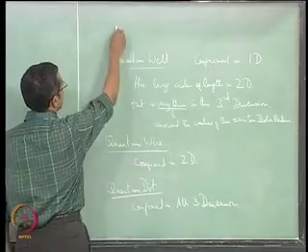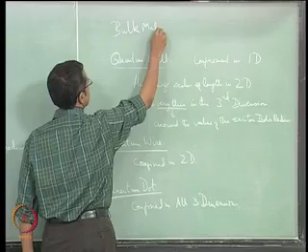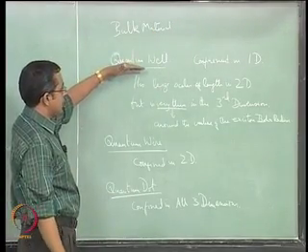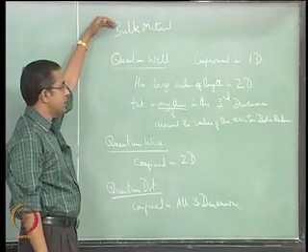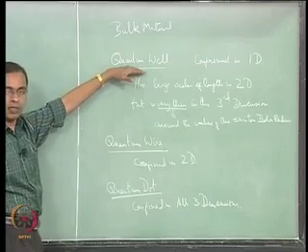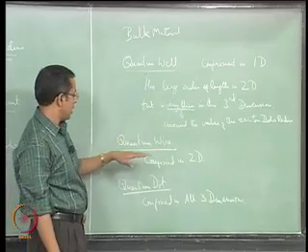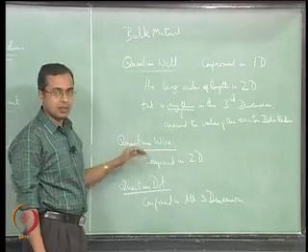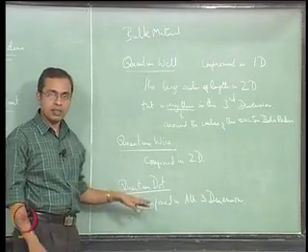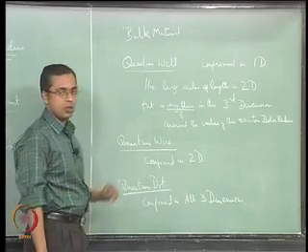Okay. So on top we have the bulk material, where there is no confinement at all in any of the 3 dimensions. From that we can convert to a material where confinement of the exciton occurs only in 1 dimension, that is a quantum well, typically a very thin film of the material. You can confine it in 2 dimensions, that is a quantum wire, which is a very thin wire, and then finally you can confine it in all 3 dimensions, in which case you essentially have a tiny particle of the material, and that is called a quantum dot.